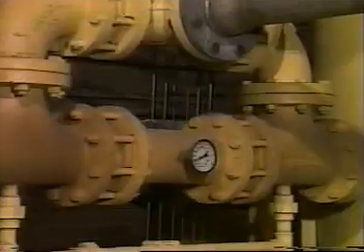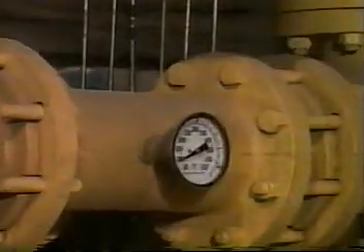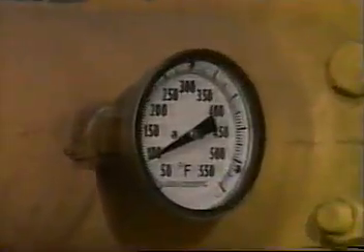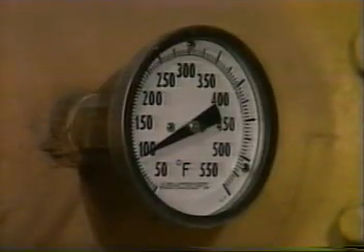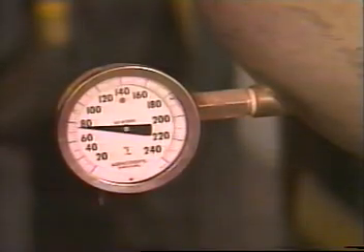Industrial bimetallic thermometers are mechanical devices. Most work on the principle that when their temperature is changed, different metals expand or contract at different rates. Here we see a thermometer sensing element made of two dissimilar metals bonded together. When the element is heated, the two metals expand. But if one of the metals, the lower one here, expands more than the other, this causes the element to bend. In an industrial thermometer,